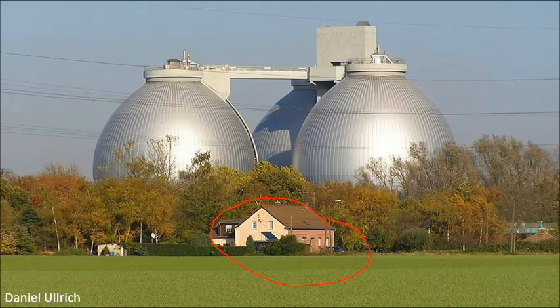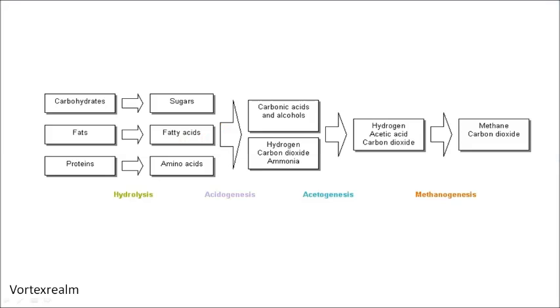But a lot of times these vessels are heated or they're buried partially underground to help maintain a higher temperature. And the reason that's useful is because first of all, it increases the rate of degradation of organic material that's in the sludge, and it also can kill pathogens if the temperature is high enough. So the diversity of microbial anaerobic metabolisms that are usually exploited in these sludge digesters also means that you're going to get a large quantity of gases and other types of metabolic byproducts building up inside of the bioreactor that you have to deal with.